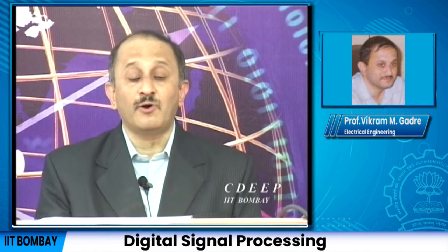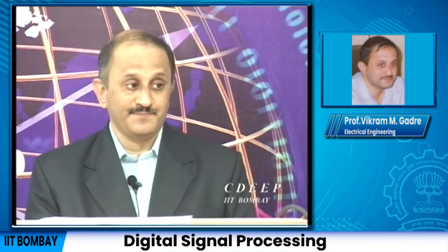So, the beauty is that with this interpretation of the operation of convolution, I also have an interpretation for how the impulse response describes the system. For a finite length impulse response, it is very straightforward. It tells you that the output at any point becomes a linear combination of the input at that point and a few points around it.